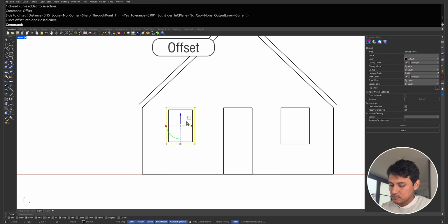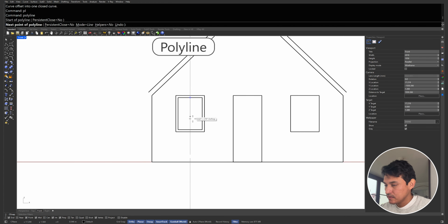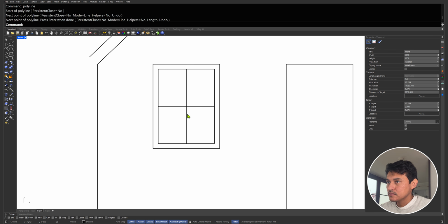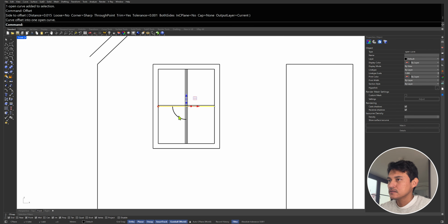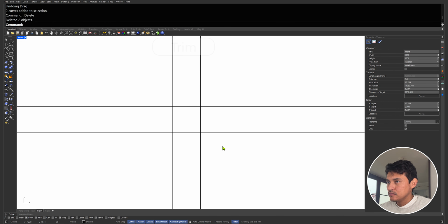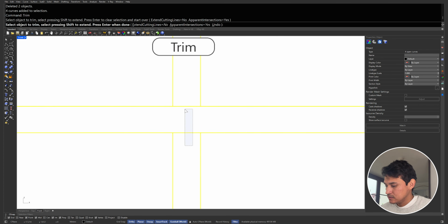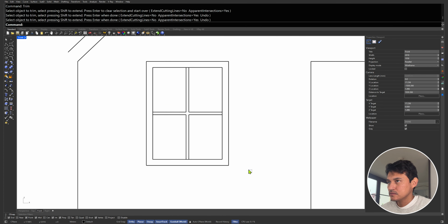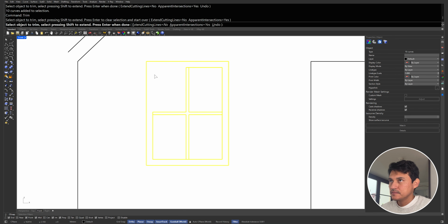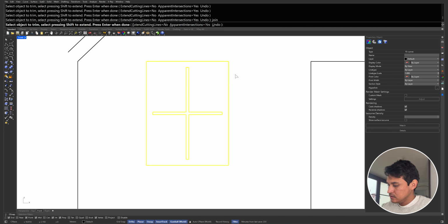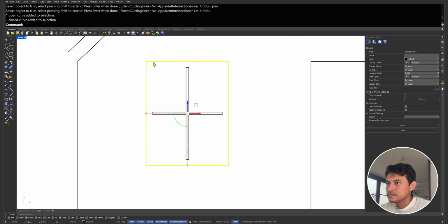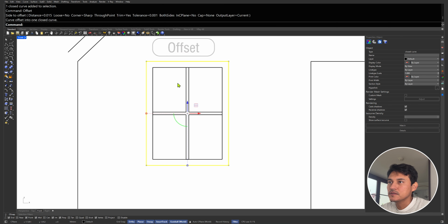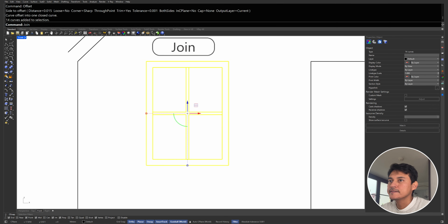Let's make an offset of 0.07, sorry, and some subdivision there. This is done. The purpose of this is that we want to get as much information as possible to continue with the next steps, which would be making extrusions and so on. 0.07. Okay, so those profiles are enough for start building this house in 3D.